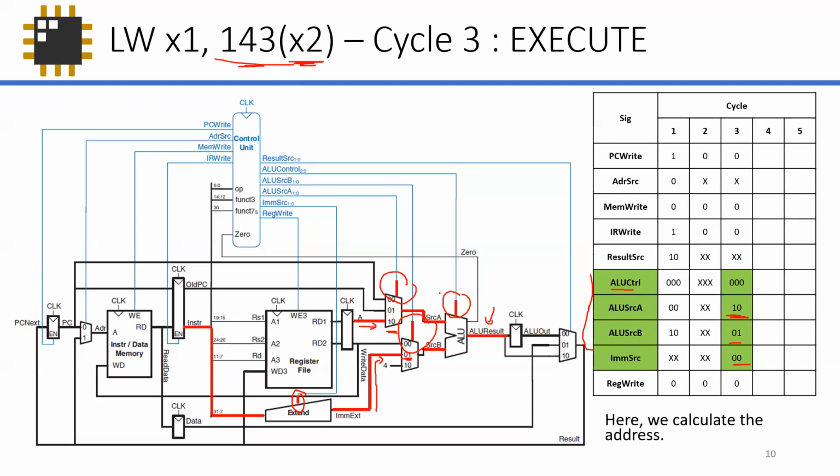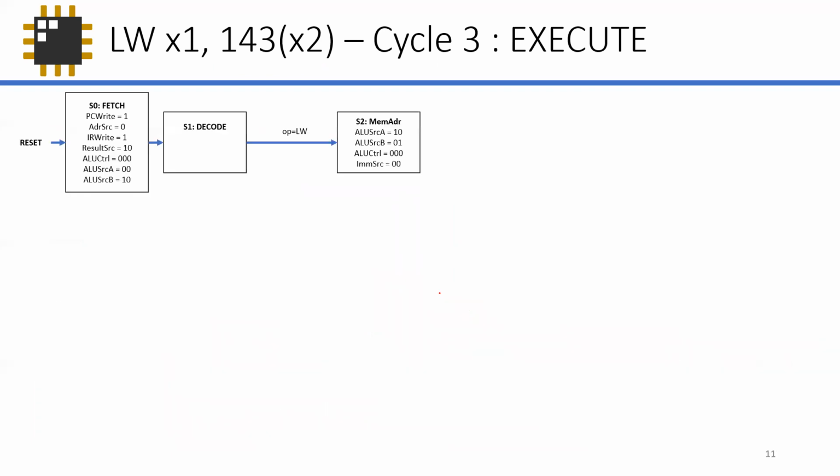Okay, so that's pretty much it. The story sort of goes over and over again. So grab those important signals, put them into the next state, and that's the only thing you have to watch out for. And then make sure all other signals are zeros or don't cares. Just make sure you're consistent with the signals.